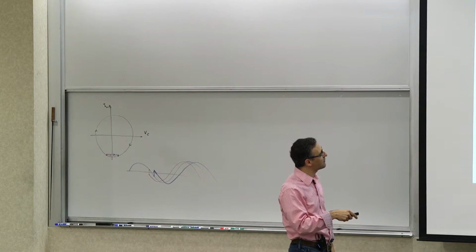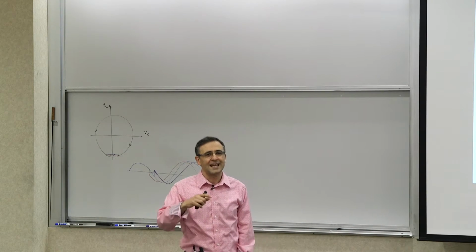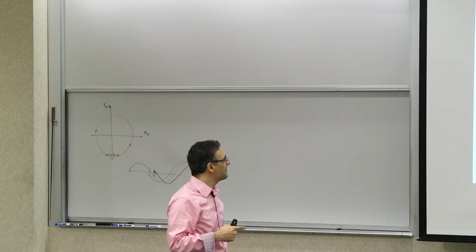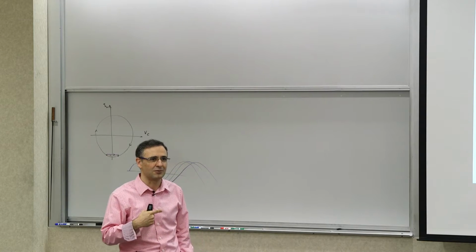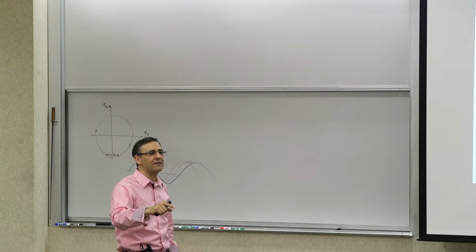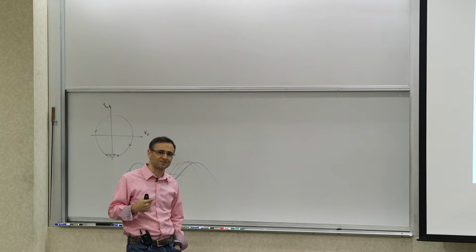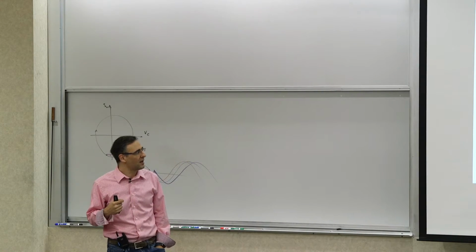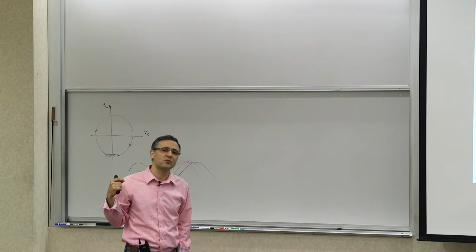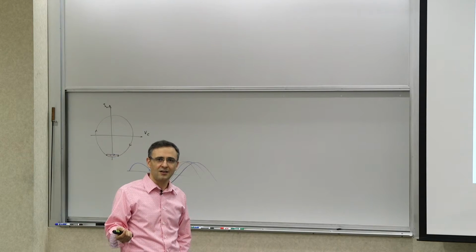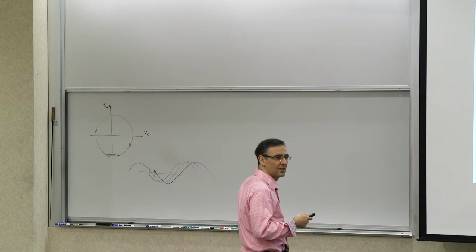In state space, the way it's described, we call this a limit cycle. In that trajectory that you traverse, there's an ideal orbit, a stable orbit, which if you deviate from, you eventually go back to. So the amplitude fluctuations get suppressed, even in a realistic oscillator. But the phase fluctuations will not, because the oscillator has no way of knowing its previous phase when you hit it. So the phase fluctuations will persist.